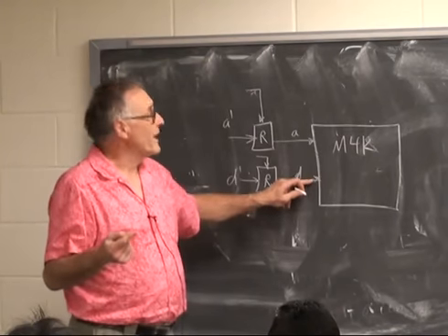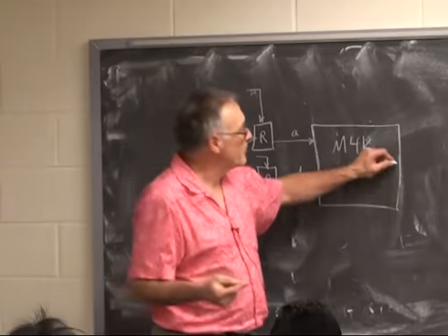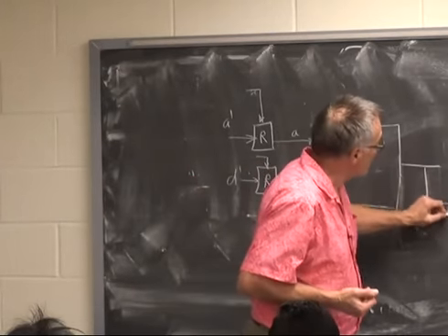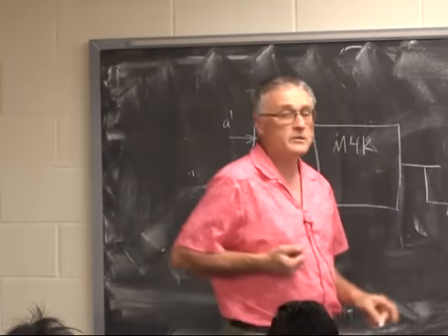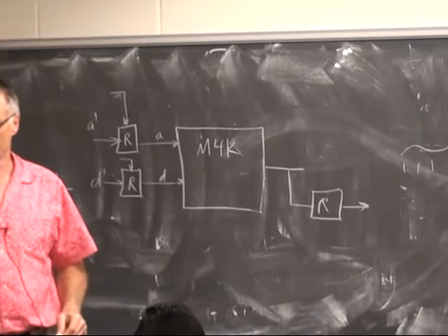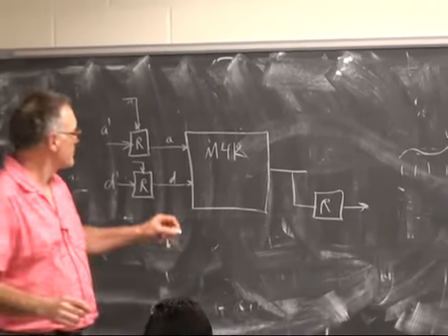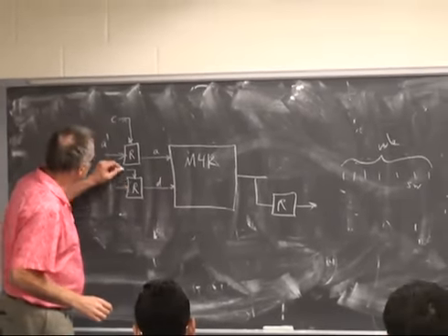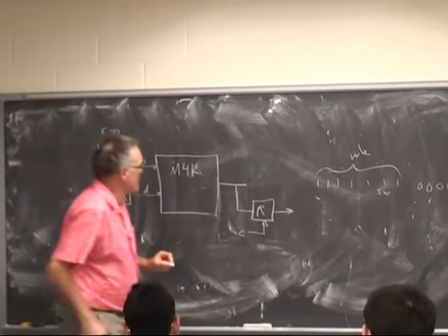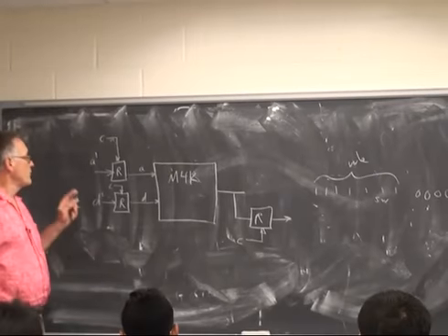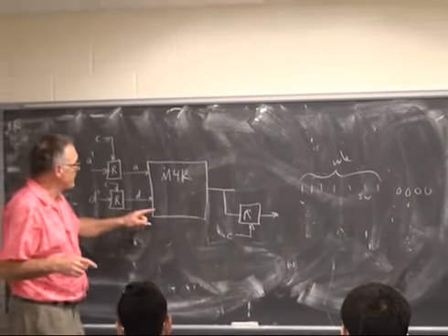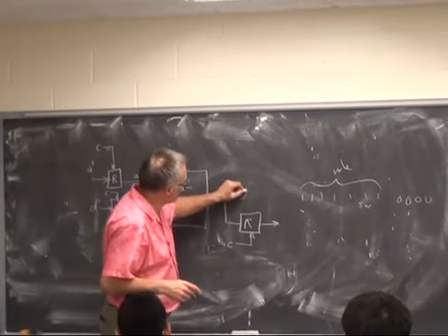One clock cycle after that, the data appears at the output of the M4K block, unless you have asked for the output to be registered, in which case there is yet another cycle before it is available. So 2 cycles after you ask for data, you can read the data here.